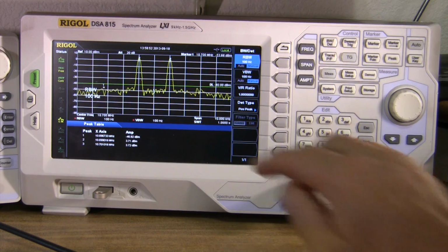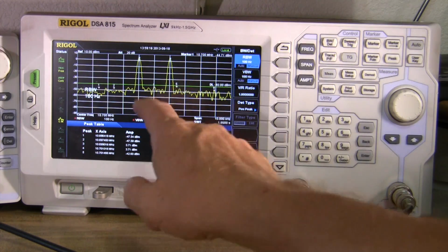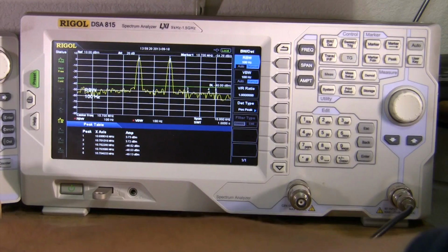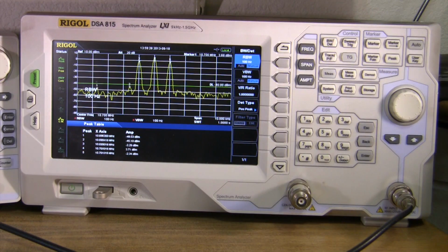Notice that the peaks have gone up to the same level of 3.71 or so that we had for the carrier on the AM. That's one thing about this arbitrary generator that's sort of interesting. It doesn't modulate 100% on the carrier that you have. The peak is set to the same level in either case. So if I turn off that, you'll notice that this now comes up to that level, and these guys are down by 6 dB. So apparently it's looking at the peak of the envelope, not at the actual carrier level. And that's, I don't know if you want to call it a failing or a difference, let's say, between this and, say, a signal generator, which should have the peak envelope power go up.